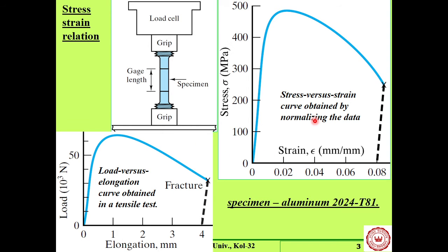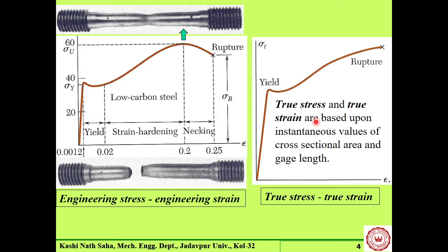This is some of the material properties we have seen in earlier discussion. This is how we measure the stresses and strains, and what we have used so far is this particular measure, which is engineering stress and engineering strain. These measures are carried out with respect to initial gauge diameter and initial gauge length. We have seen that there are 2 points on this specimen. The distance between them before deformation is known as gauge length, and this diameter is known as gauge diameter.